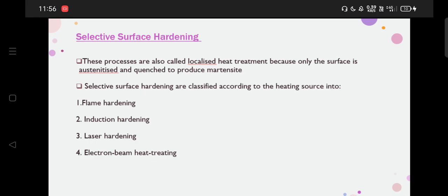Tempering can be done to eliminate brittleness. The depth of the hardening can be increased by increasing the heating time. As much as 6.3 mm of depth can be achieved. In addition, large parts which will not normally fit in a furnace can be heat treated.